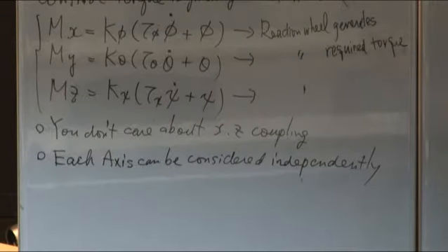In the bias momentum system case, the x and z axis coupling is stronger, because of not omega 0, but the h. There is an internal angular momentum around the y-axis that makes a very strong coupling between the x and z axes for the bias momentum system case. But for the zero momentum case, that h does not exist.